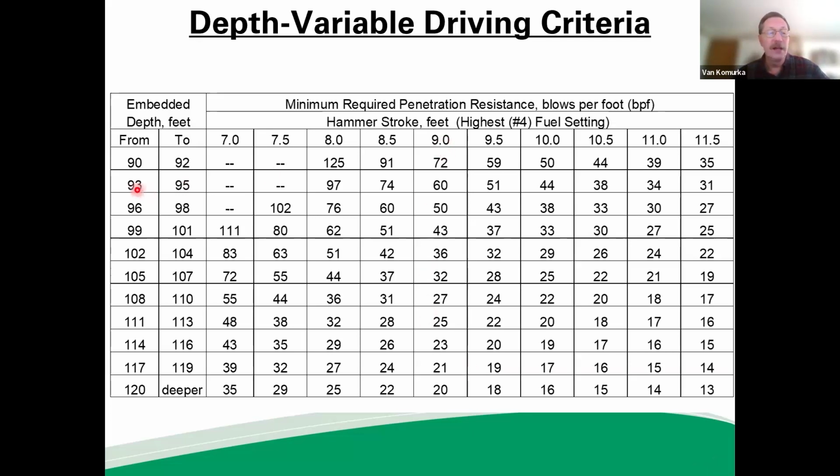Now the setup was coming on very fast, so we're breaking down the depth intervals in 3 feet, because remember we were getting 5,000 psf per foot, or I'm sorry, 10 tons per foot at 5,000 psf, so 10 tons per foot of embedment. So we broke the elevation intervals for this table down fairly small,